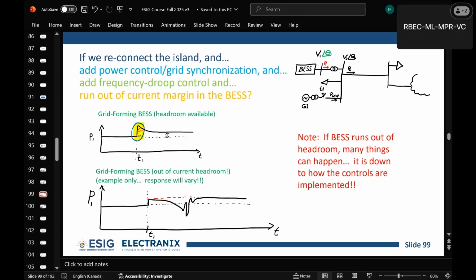So if you're in Hawaii, you're the only grid forming plant in existence, and they're putting horrible faults on the system that last forever and include phase angle jumps, you need to really take care of this problem, okay? And if you look at some of the tests that we're going to talk about later, we focus particularly on how current limiting is done to make sure that you do it in a stable way and you don't cause more problems than you're solving.